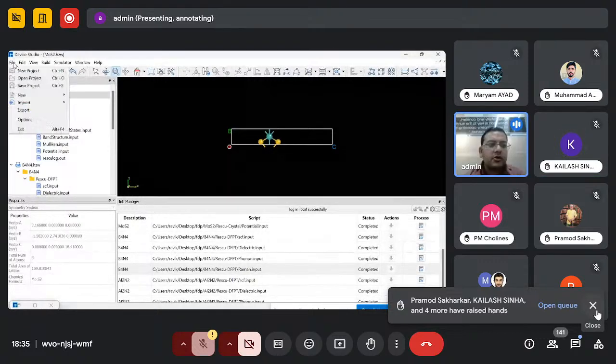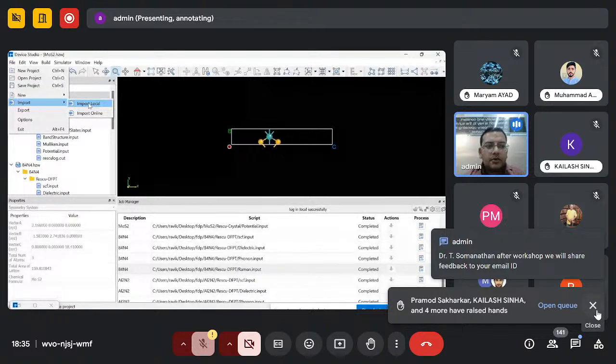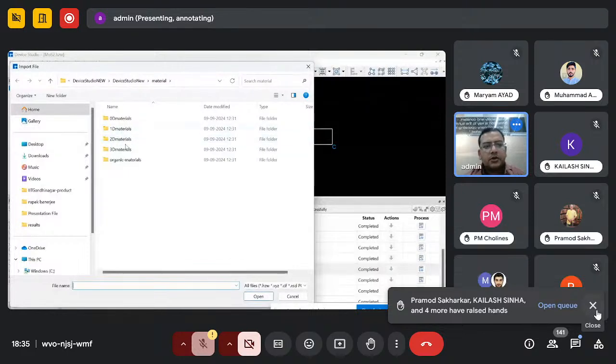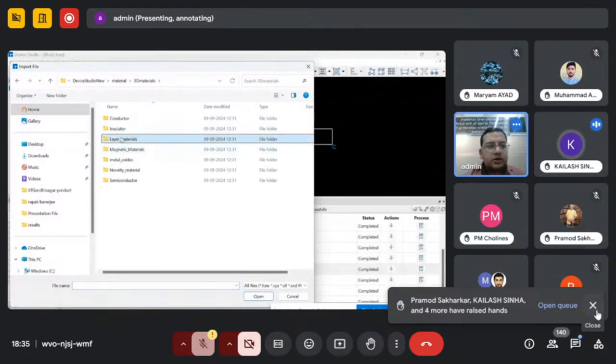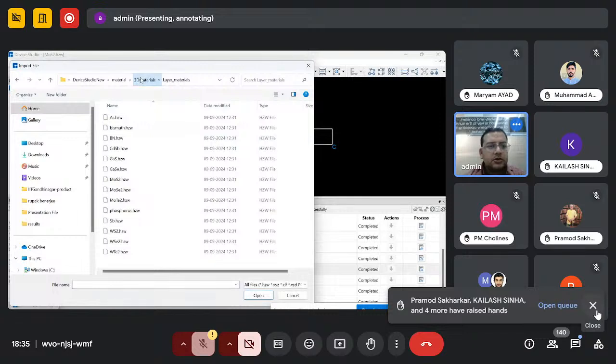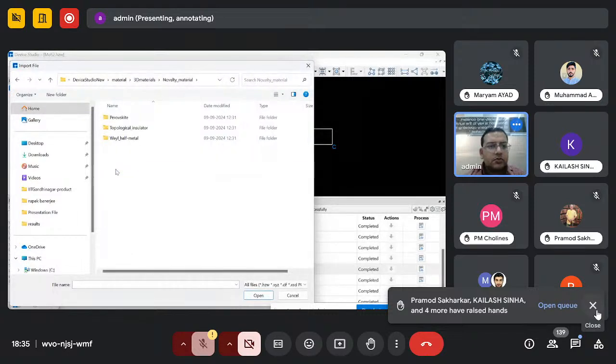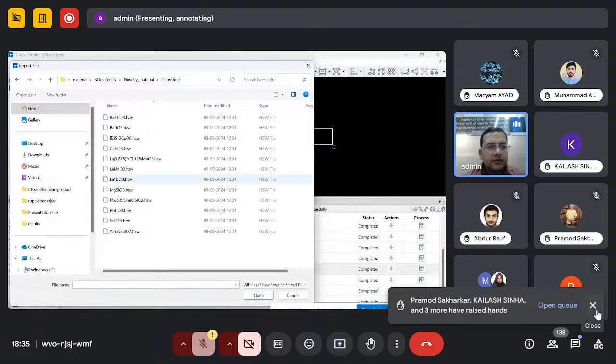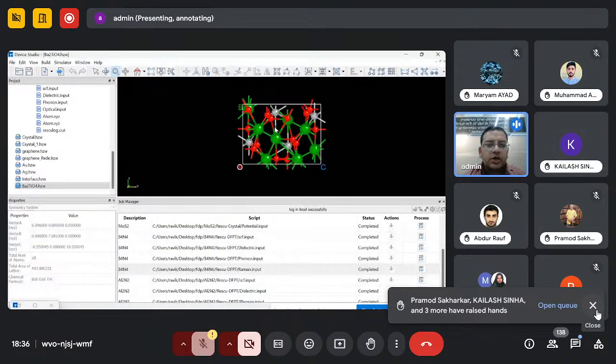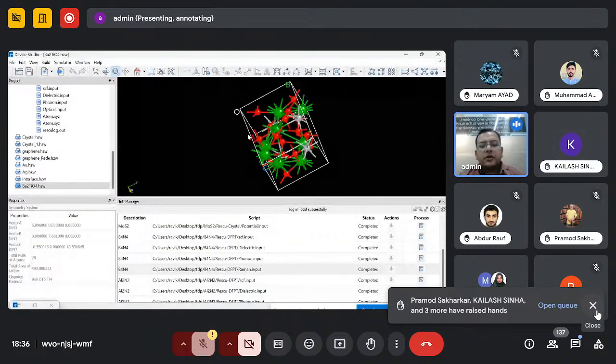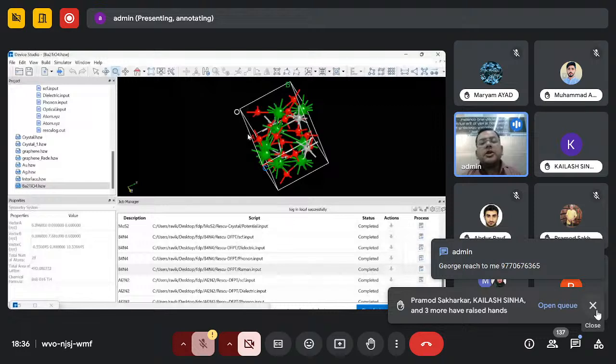Basically, this software can work only for material property prediction at the atomic level. Let's suppose you want to work on perovskite. This is a layered material; different perovskite materials are given in our library. If you want to simulate these perovskite materials and their electronic, phonon, Raman, and optical properties, it can calculate them. Even atom-based device simulation can be done, for a photodetector.